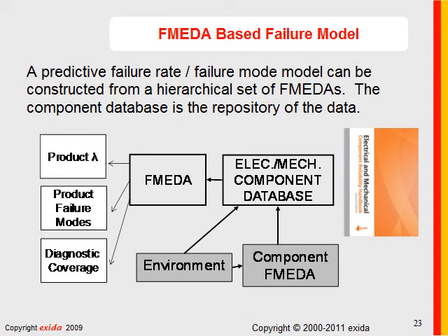I see a question. Is it possible to allow for redundancies in the FMEA? The answer is yes, but you do have to be careful because an FMEA only considers one component and one failure mode at a time, much like the original FMEA. The reason for that is if we try to deal with combinations of two failures or more, the analysis explodes into what I've called virtual infinity and becomes truly impractical.